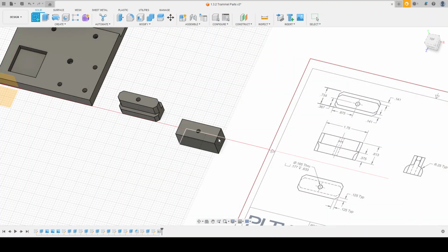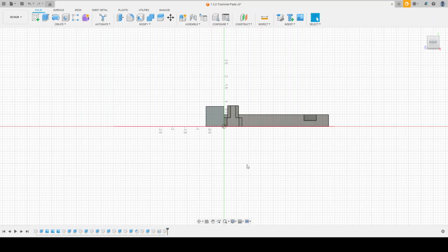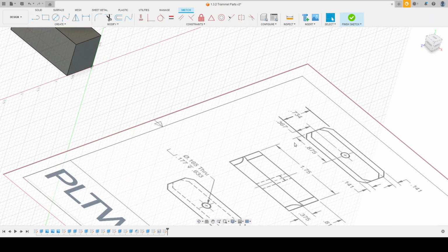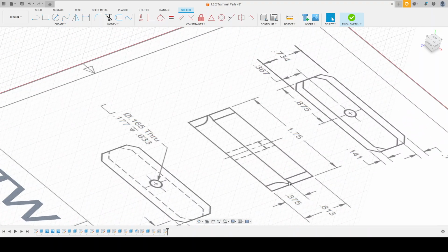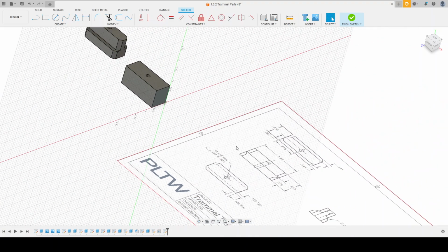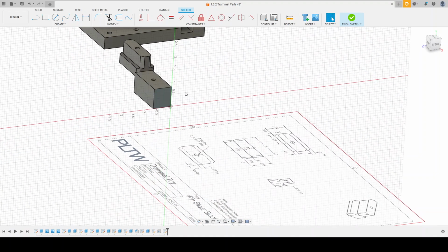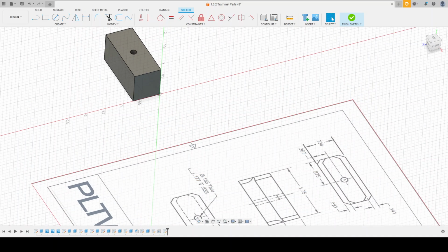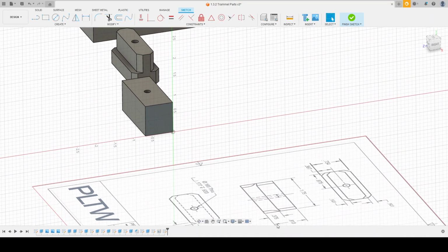So now we're going to create another sketch. We're going to do it on this front face, or rather the right face. And we're going to cut off those two shelves like we did previously. A little bit more difficult to make happen. Since we have that round over, we need to keep it present. So to make that happen, we're going to just cut it as if it doesn't have a round over. And then I'll show you how we add the round over onto it afterwards. So 0.141, again, is how far that shelf is. And then 0.375 is how high up it needs to be.